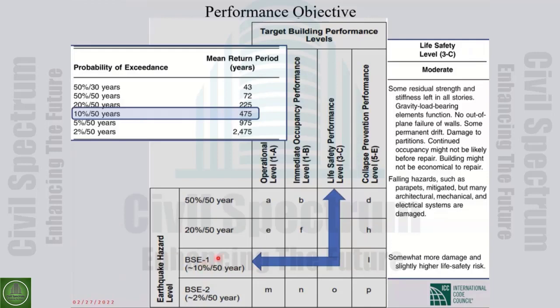The demand part is we need a formula that transfers the level of earthquake to a level of force that should be applied to the building, the base shear. So we need a formula to give us the base shear, exactly the same approach that we have for design of new buildings. Then we apply this base shear distributed to the building and look at the different demands for the force control parameters, displacement control parameters.